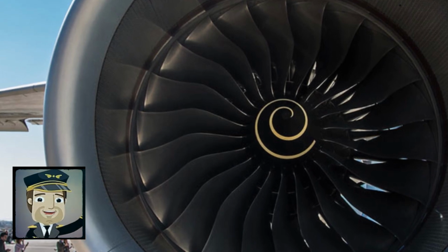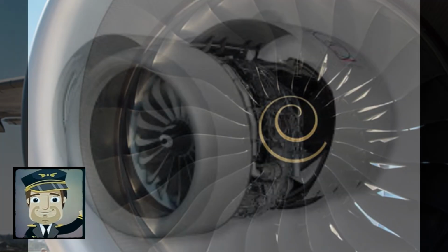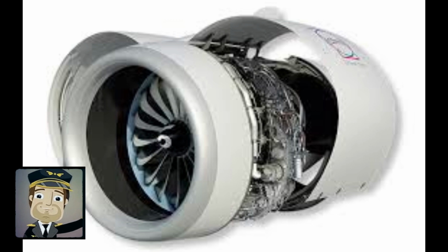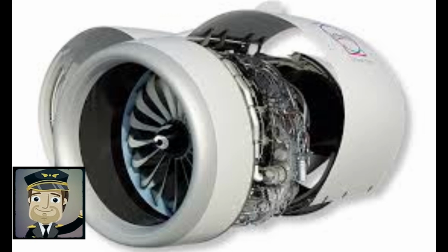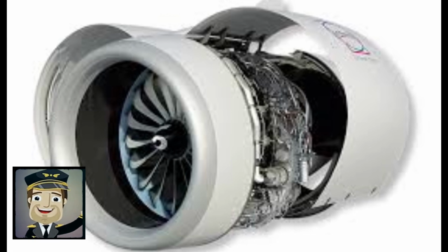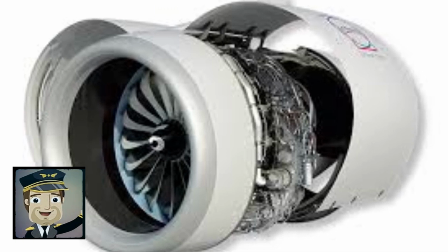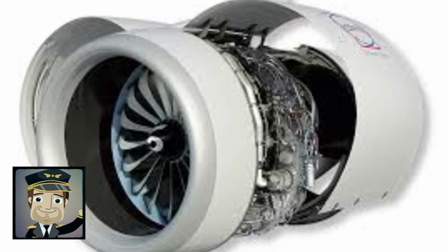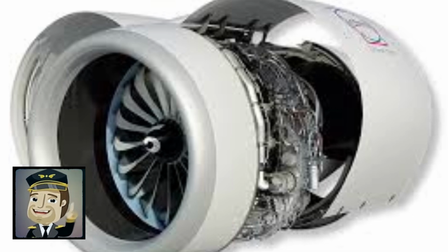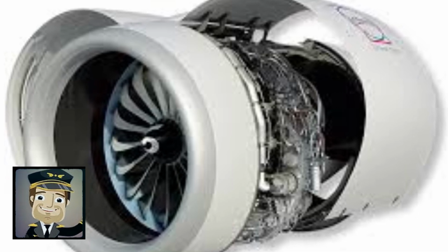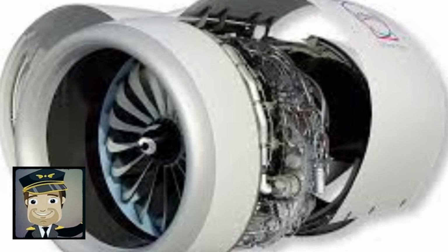Later in 1943, the British ground tested the Metrovic turbofan, which used a Metrovic F.2 turbojet as a gas generator with the exhaust discharging into a close-coupled aft fan module comprising a contra-rotating LP turbine system driving two coaxial contra-rotating fans. Improved materials and the introduction of twin compressors, such as in the Bristol Olympus and Pratt & Whitney engines, increased the overall pressure ratio and thus the thermodynamic efficiency of engines. They also had poor propulsive efficiency because pure turbojets have a high specific thrust, or high velocity exhaust, which is better suited to supersonic flight.